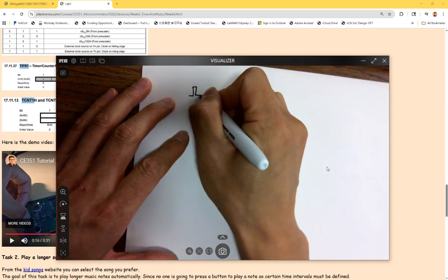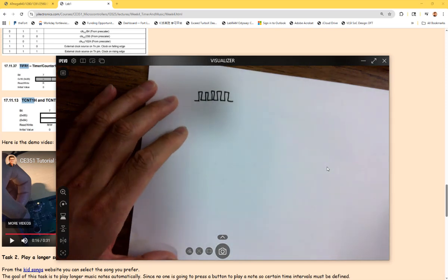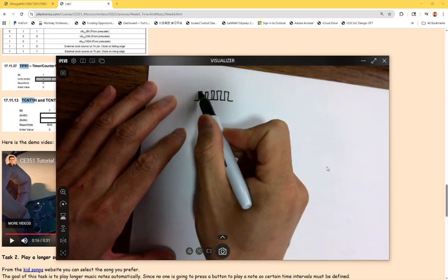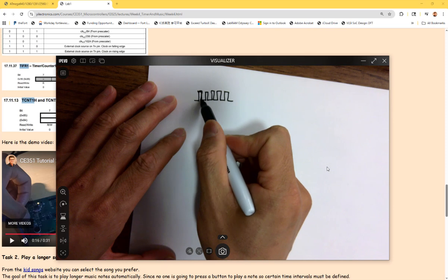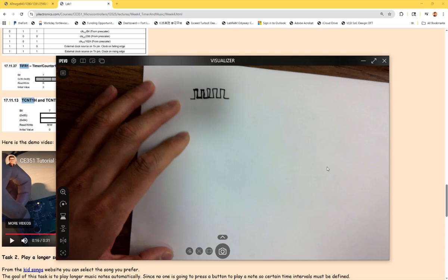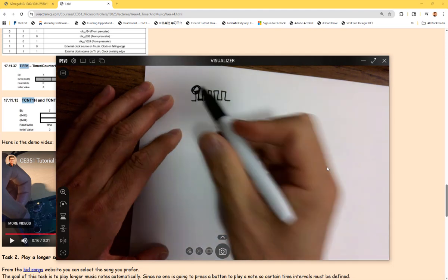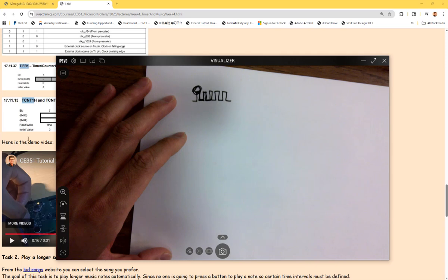It's basically like toggling with a certain frequency for a certain pitch, right? After you do this: time delay, toggle, time delay, toggle, time delay, toggle. That's how I handle that. So you can use microsecond time delay. A second method, if you watch the video here.